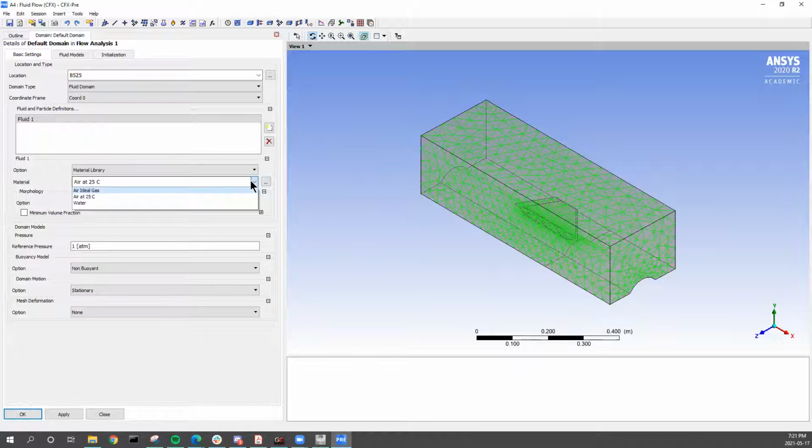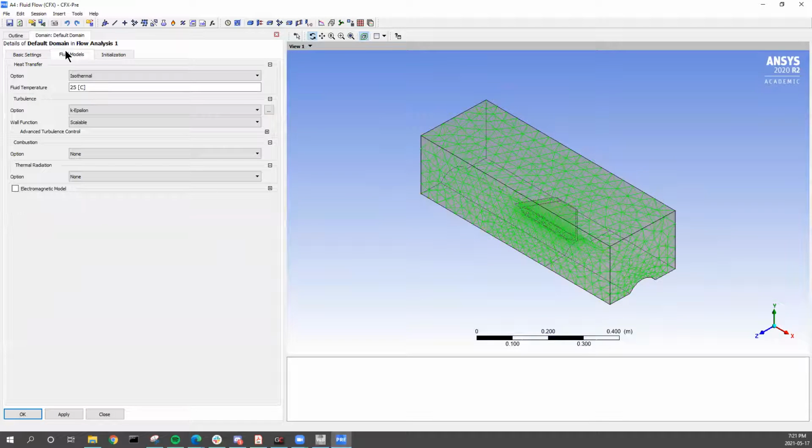This is actually supersonic flow, even though it's a 10K rocket. It is about Mach 1.2 max speed. So change to air as ideal gas. Basically, there are all these relations for Mach number and supersonic flow that assume air is an ideal gas. So if you use that assumption, you can use the supersonic models.